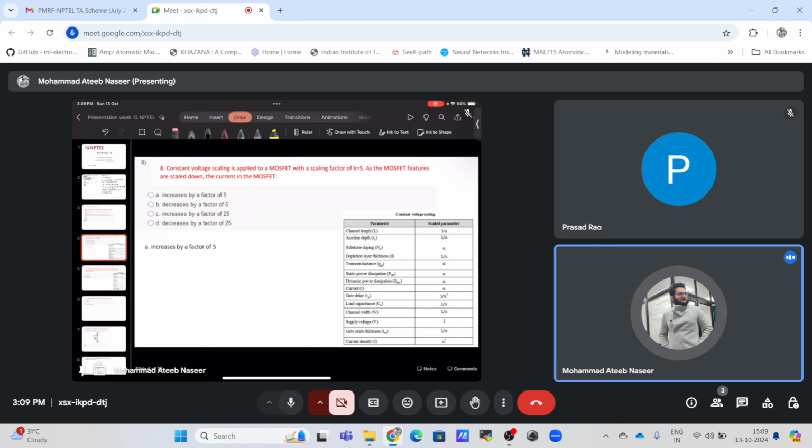For example, we had a planar structure previously, for example, when we studied a single gate device. Then we can have a double gate device, that is, there will be a gate on the top as well as the bottom. Also we can have a gate all around device, where we have the gate around all the channel. So that is known as the gate all around device.